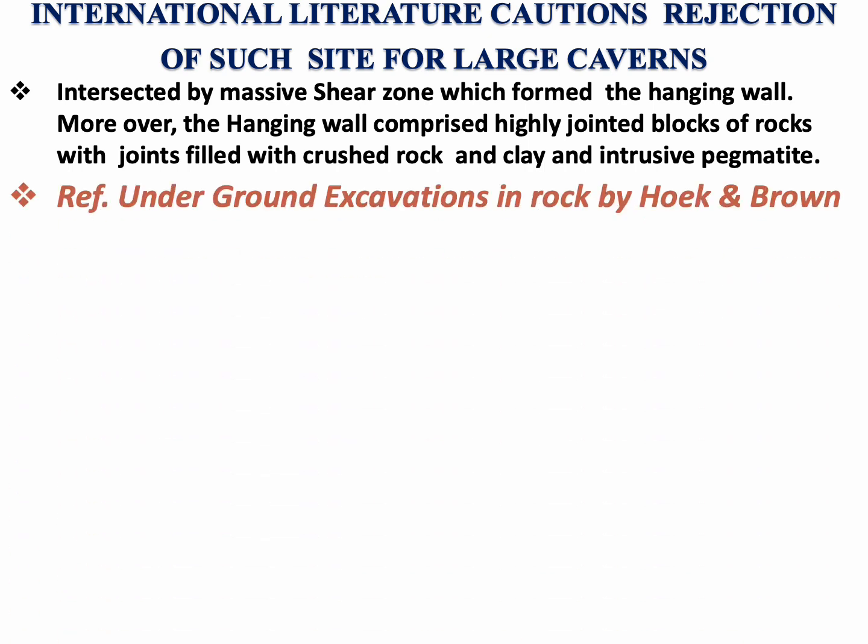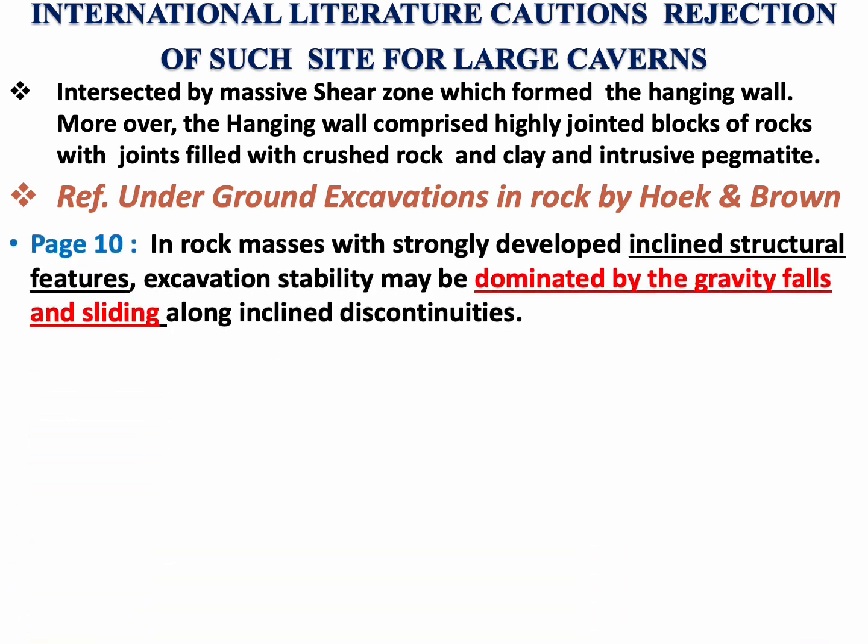Such conditions, if compared with what is mentioned in Underground Excavations in Rock by Hoek and Brown, at its page 10, the literature mentions: in rock masses with strongly developed inclined structural features, excavation stability may be dominated by gravity falls and sliding along inclined discontinuities.